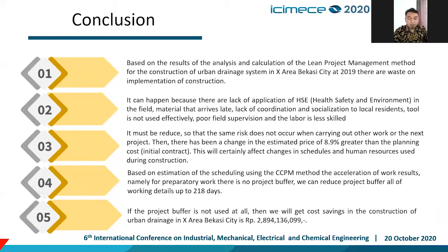This will certainly affect a change in schedule and human resources used during the construction. Based on the estimation for the scheduling using the CCPM method, the acceleration of work result, namely for preparatory work, there is no project buffer. We can reduce project buffer of all working details up to 118 days. If the project buffer is not used at all, then we will get cost saving in the construction of urban drainage in X area Bekasi city of more than 2 billion rupiahs.